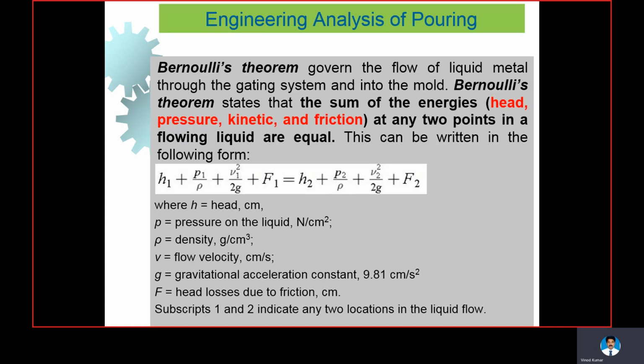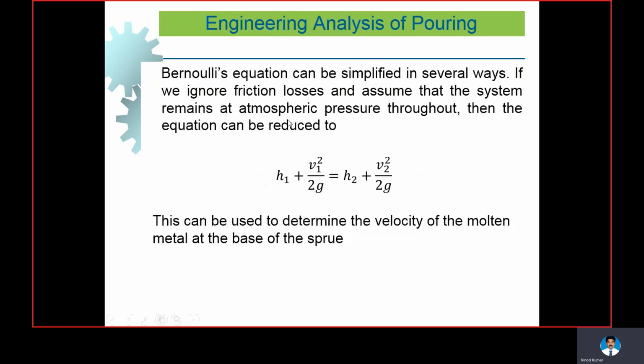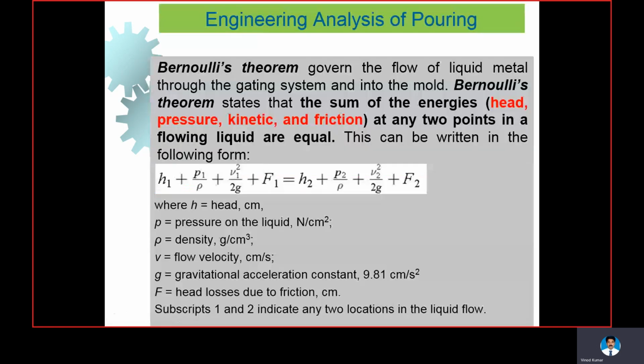Now, the analysis of pouring. When we analyze the pouring, we have to apply Bernoulli's equation, the flow of a liquid, fluid mechanics concepts, to understand the pouring process. So in a pouring process, let us take 2 sections. One section is the pouring point. At that point, we can say section 1, we have